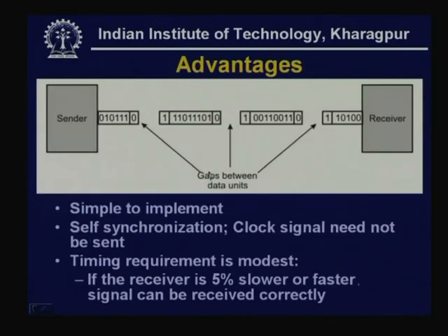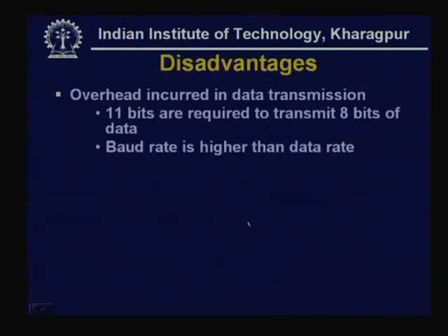And as a consequence, the timing requirement is modest. Even if the receiver clock is 5% slower or faster, the signal can be received correctly, because the synchronization is done for each character separately at the beginning of each word. But it has some limitation.